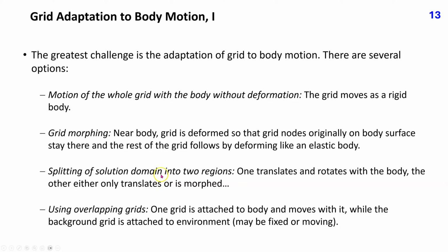Splitting of solution domain into 2 regions. One translates and rotates with the body, the other either only translates or is morphed. And using overlapping grids. One grid is attached to body and moves with it, while the background grid is attached to environment. It may be fixed or moving.